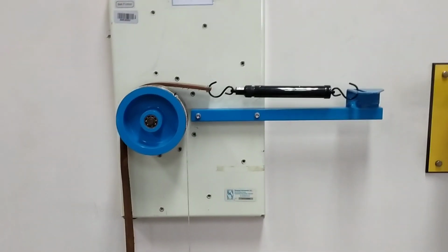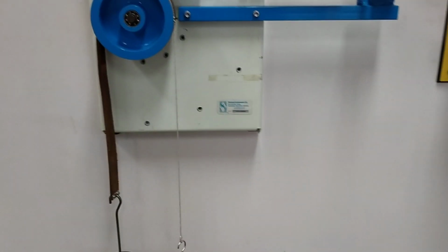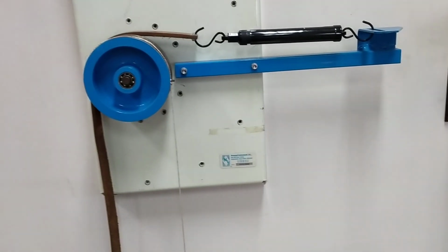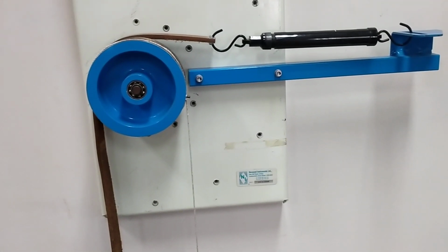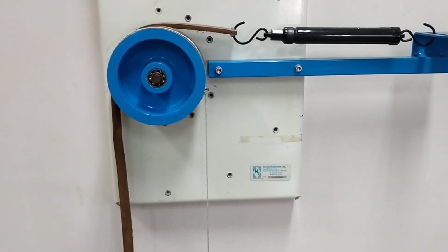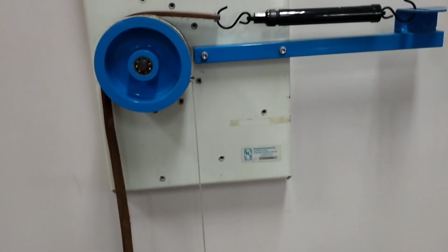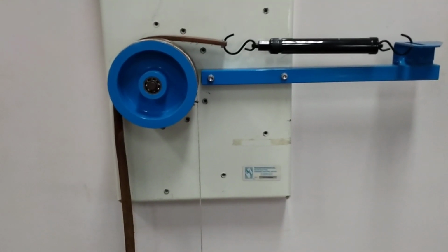Hope that's clear. One thing more to counter your answer, this is just a check to approximately check your experimental values: the difference between T1 and T2, that is T1 minus T2, basically 10 Newton and that's 550 grams, so that would be approximately 5.5 Newton. If you take the difference of the two, it comes to approximately 4.54, which equals this distance. So this means you get an approximate answer for the T chord, which means your values are quite accurate.